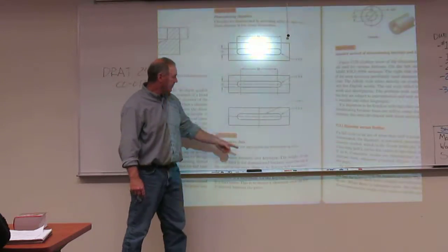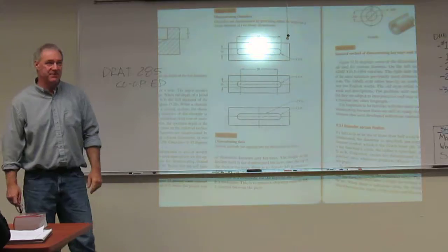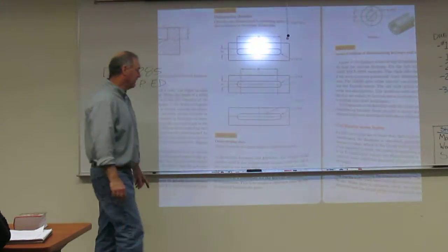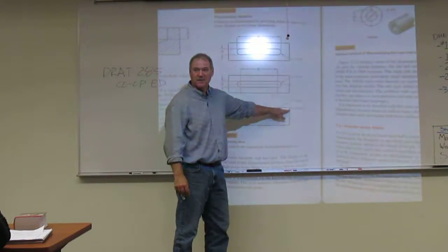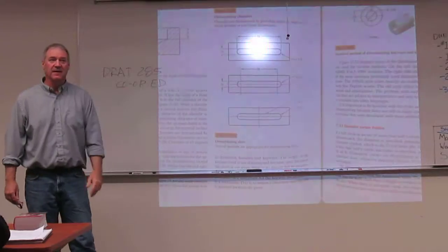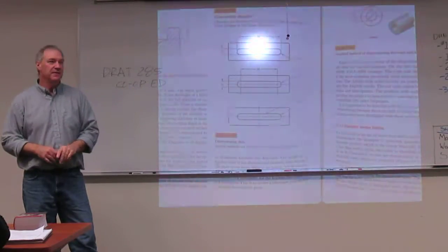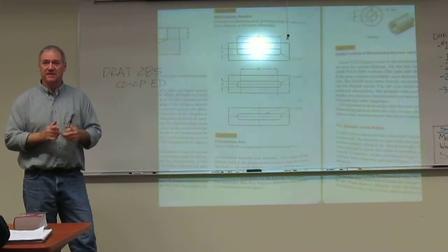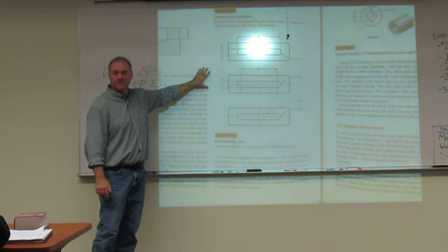If you don't have a lot of room, we can go to leader lines for basically the same information, where this is giving width and length, and this is also giving width, but it's also calling out a device. Because I can build this a lot of different ways. I can cut it with saws. I can then drill just the ends, or I can use router devices, I can use CNC. So use one of these three when you dimension your slot.